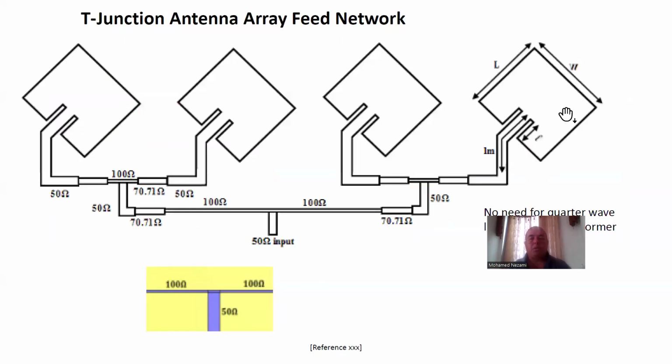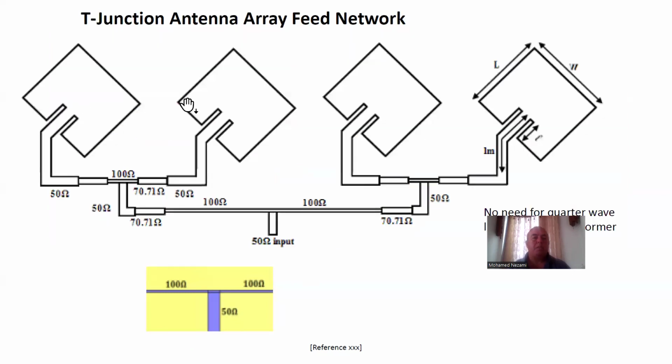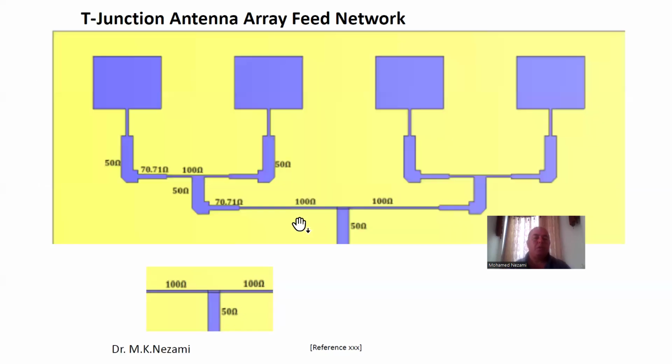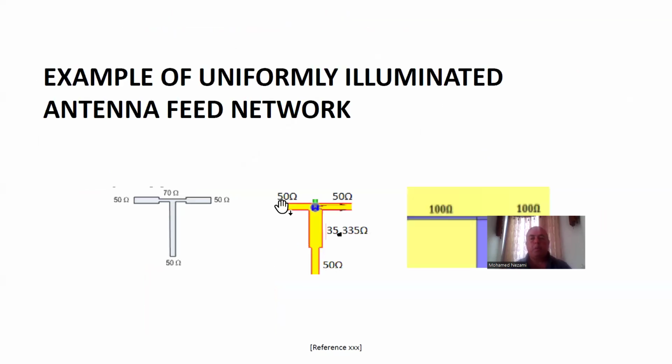Now, likewise, just like we said before, it's exactly the same feed. Now we're feeding this type of antenna where we are controlling the inlet here, the inlet feed point, so that we get 50 ohm. This is 50, so we can use it directly, so it's much less. It reduces the dimensions of this because we don't need to use an additional transformer to transform the antenna element impedance to the feed line point.